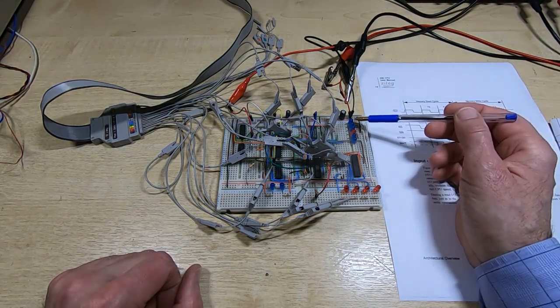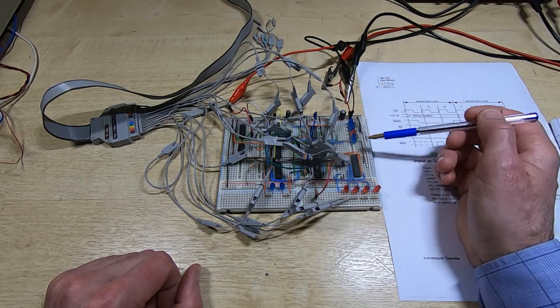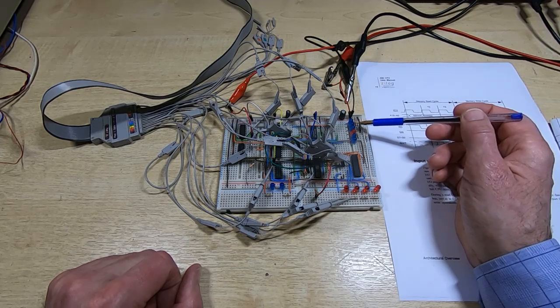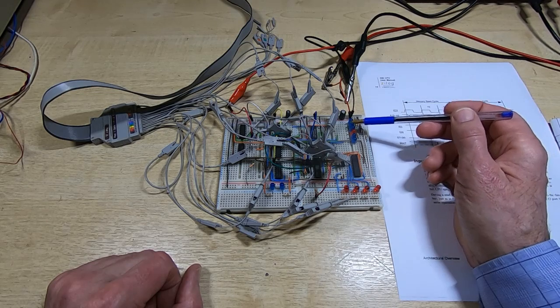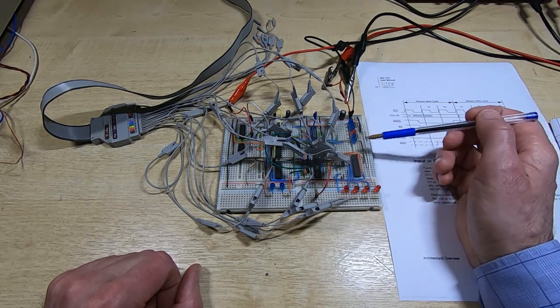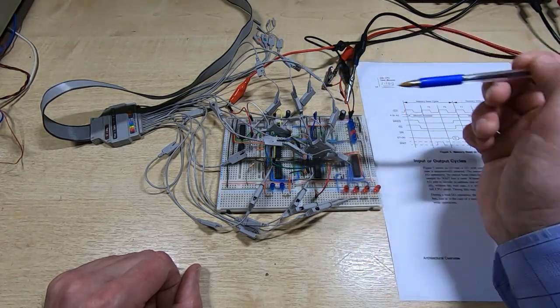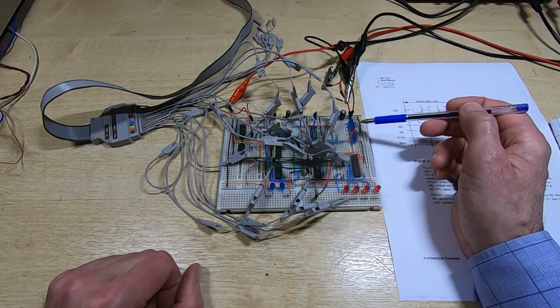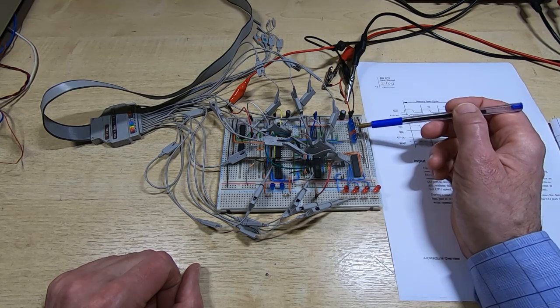So these LEDs, the top one is the read enable that goes to the floppy drive interface device. The next one down is the write enable, the next one down is the chip select. So these three are the lines going to the floppy drive controller, so that either the DMA can access it or that the Z80 can access it directly if we're using the in-out commands to program the floppy drive controller.